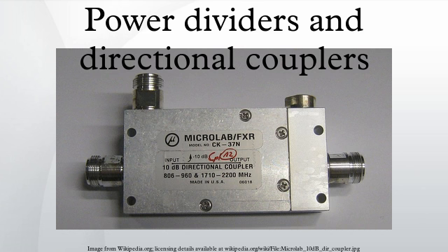Moreno crossed-guide coupler. The Moreno crossed-guide coupler has two waveguides stacked one on top of the other like the Bethe hole coupler but at right angles to each other instead of parallel. Two off-center holes, usually cross-shaped, are cut on the diagonal between the waveguides a distance apart. The Moreno coupler is good for tight coupling applications.